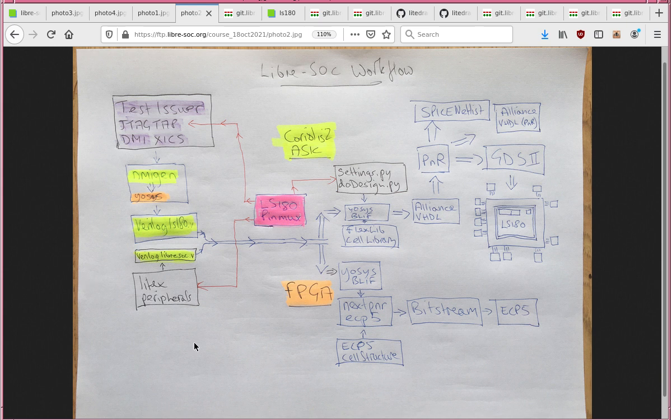On the other side, you then run another makefile command, which runs LiteX to auto-generate the LiteX peripheral fabric interconnect. Our use of LiteX has told it about the various interfaces, which we'll go over in the source code in a bit, and that will generate a LibreSOC.v file, again in Verilog.